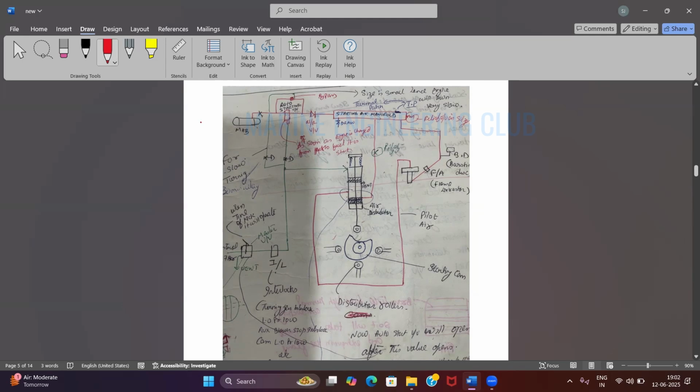So you have to achieve a minimum cranking RPM in order to have this compression pressure. And that is around 20 to 25 RPM of your engine in main engine, until your engine starts to turn only on air at this RPM. This is called minimum cranking RPM.